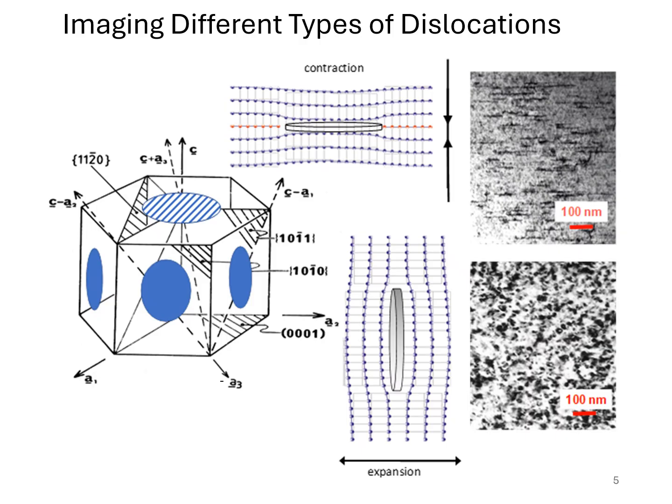And by and large, when you create point defects by atomic displacement, there are instances where vacancies cluster together in a platelet, typically on the basal plane, giving a defect structure which is characteristic of these vacancy loops.